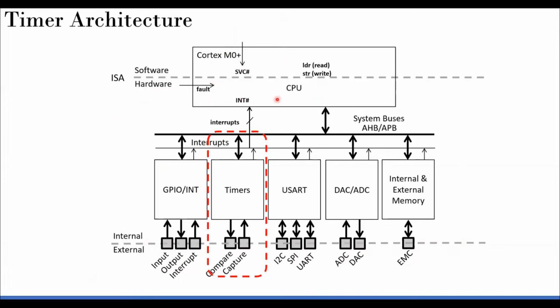You have the processor CPU core here. There is an interrupt path which goes to the NVIC. In the previous slide, we saw the nested vector interrupt controller sits here and then communicates to the CPU. The software exceptions or the hardware exceptions will come directly to the CPU. They won't pass through the NVIC, as we discussed last time. Going to this side, of course, the interrupt channel is different. It will communicate through the NVIC to the CPU.